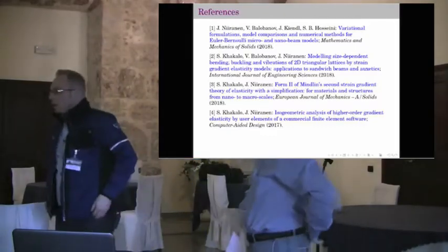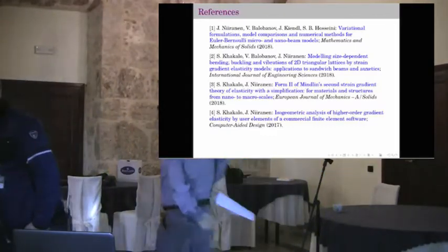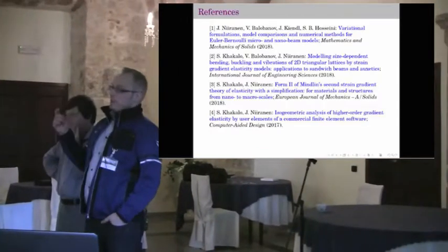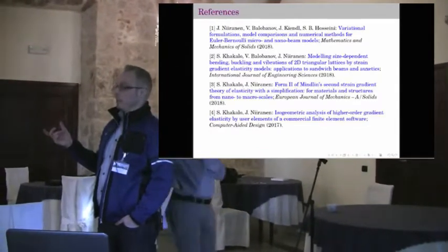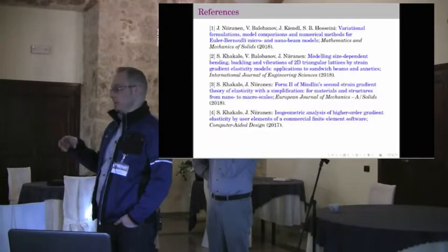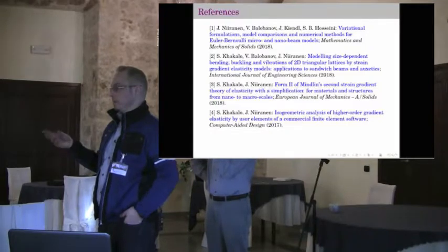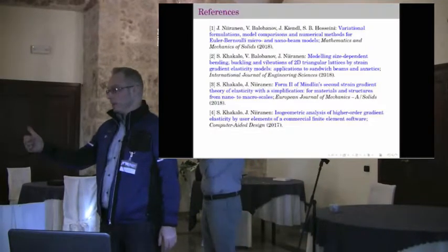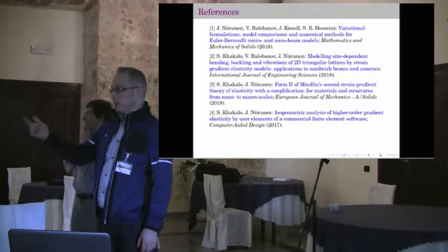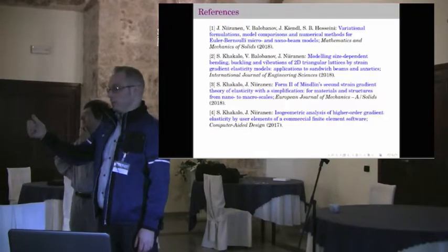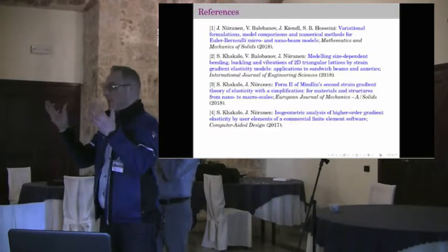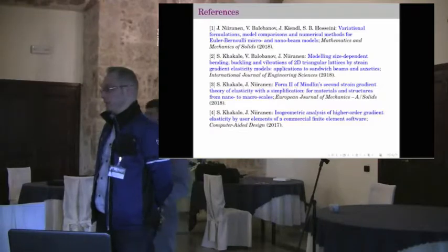So to get rid of the lock effect, we use some kind of mixed method? Well, not really mixed, because the number of variables is still the same. So it's practically, I would say, a change of variable, because after that you don't have rotation, but you have shear. And in the other one, you don't even have deflection. You have two variables which are combinations of deflection and rotation.